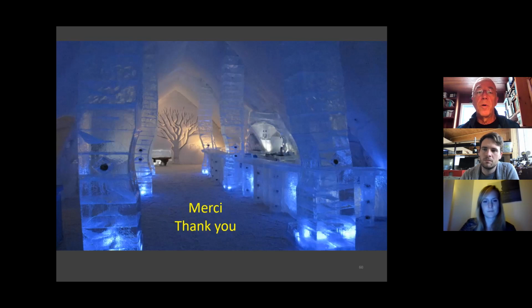There's perhaps a way to take care of that. In terms of using more durable alternatives, again, this material has proven to be very effective. I know there are new materials that are becoming available. One of them is cellular glass. It's actually foamed glass that is extremely effective. One of the problems with insulation, as you've seen in the picture, is you need to manually place down the boards. And you can imagine if you're working in the north where it's often very windy, it's extremely difficult, can be costly, can be labor intensive, there are all sorts of problems.